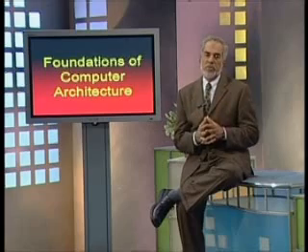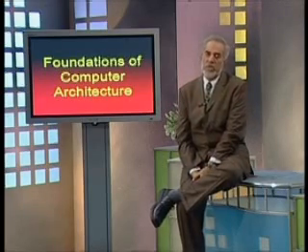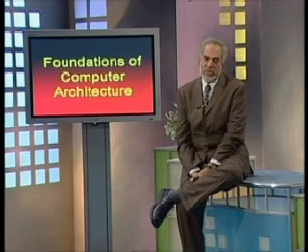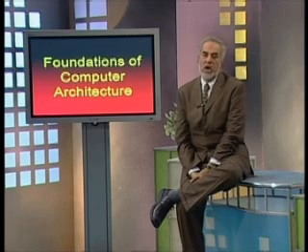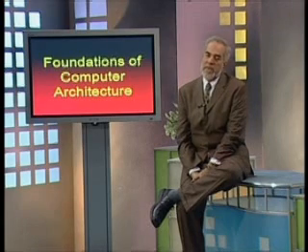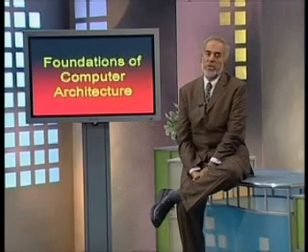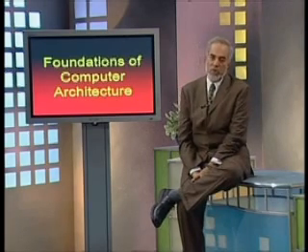It's not only the accumulator, but the status of the overall computer would be determined by other registers like the program counter, which keeps track of the address being fetched, and then an instruction register and possibly some status registers to indicate the status of different bits like overflow and so on.